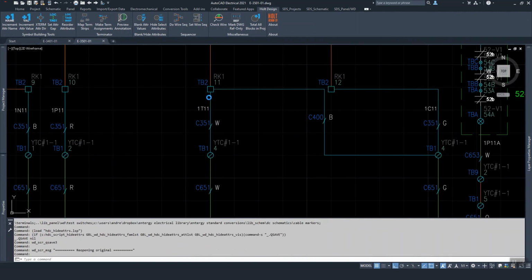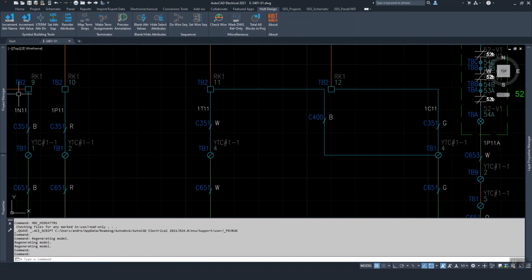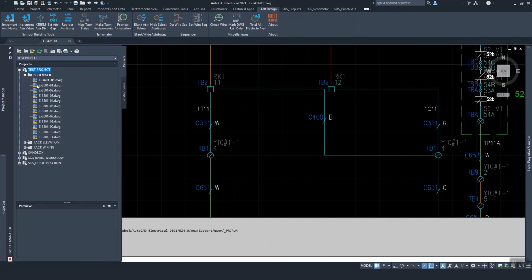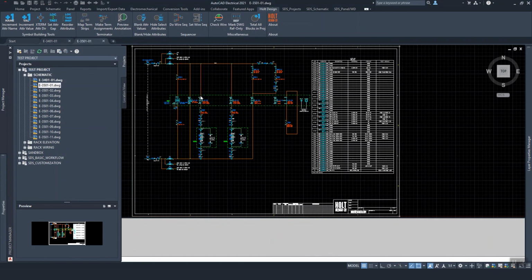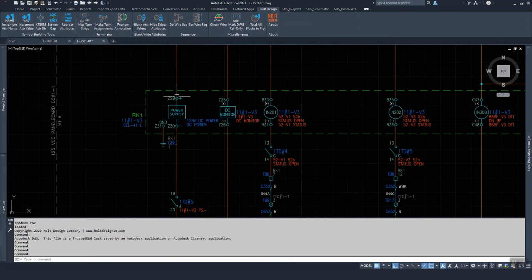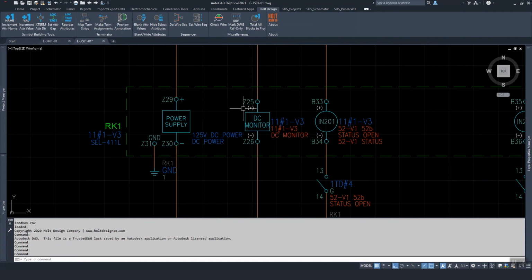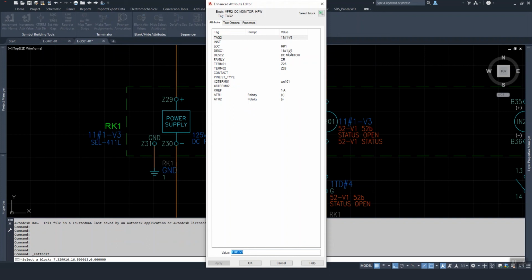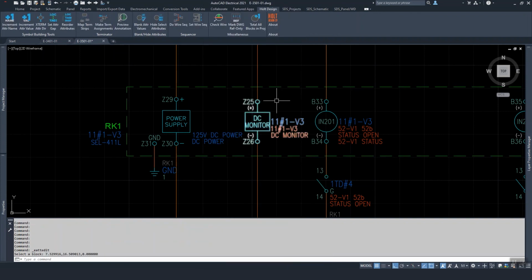And it was hard to see, but let's go ahead and open that drawing back up again now that it's been saved and closed. And all the location codes for this line of symbols right here have been marked as invisible. Here's the location code right there. You're not seeing it anywhere here.